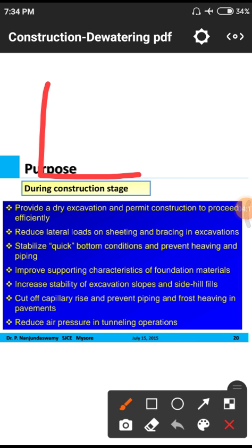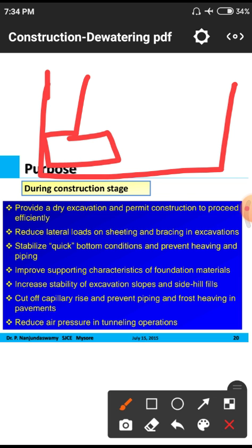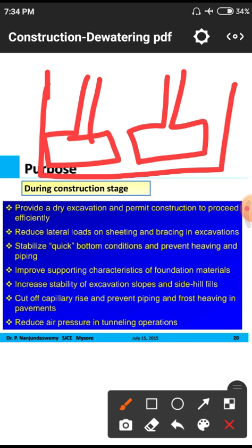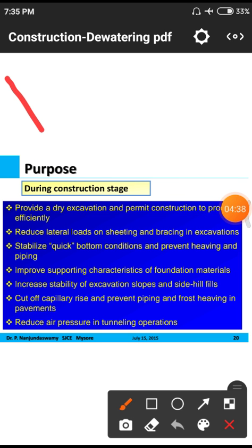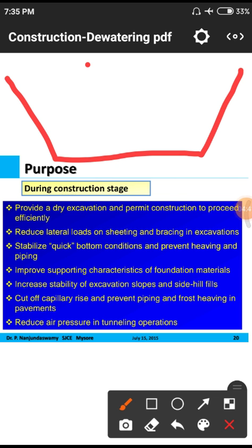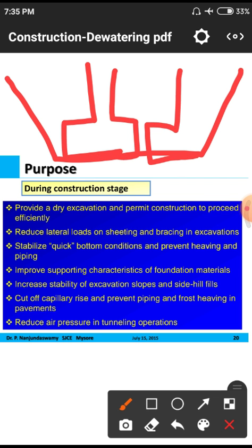Normally we have to use this kind of excavation work for footings and others. I will give a small example. There is a structure having two footings, so if the structure is located with this kind of strata, there may be some amount of matter falling onto the foundation. To prevent those falls, we have to use a sloped structure, so this is the sloped structure. In this kind of structure, we don't have material falling onto the foundation.